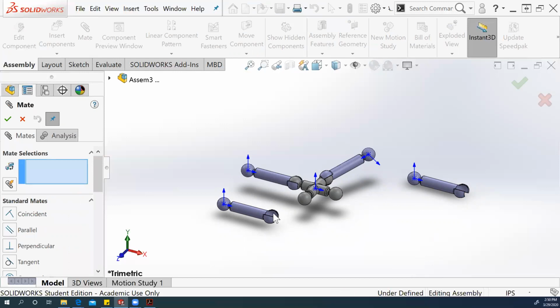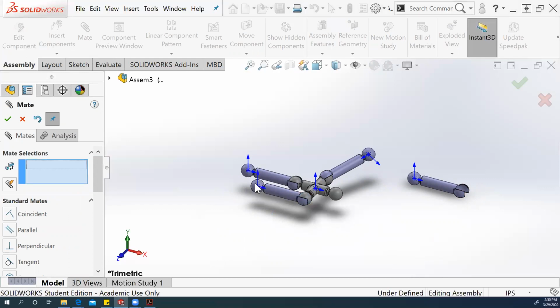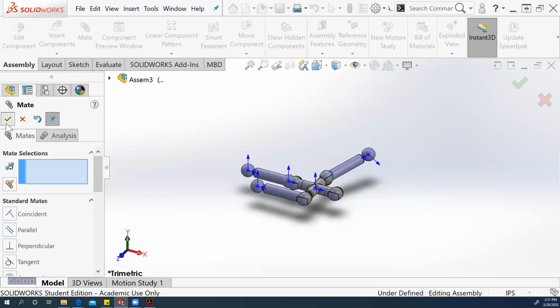We're going to click this and then this. Make sure concentric, good, check mark. And actually I'll add another mate because my mates are open. So click there and there, okay. And then it says concentric, which is good. We're gonna click add mate, and then we are done.